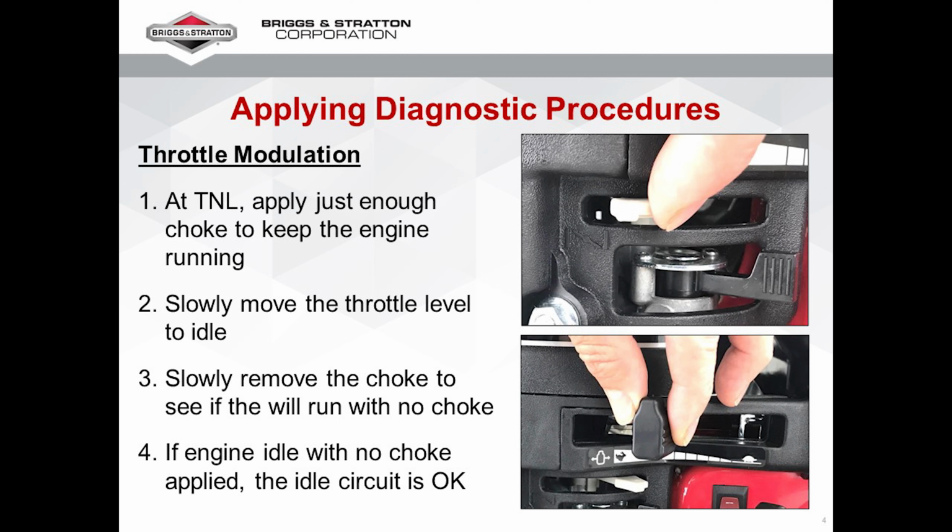By default, the high-speed circuit is where we would turn our attention to during the cleaning process. We cannot load the engine enough to get it fully on the high-speed circuit, so instead we isolate the engine to run only on the idle circuit to identify our direction. Remember this important detail: both the idle and the high-speed circuits work together to deliver the total amount of fuel during engine operation conditions above idle. If one circuit is impaired, the engine will be lean as a result, especially at top no load.